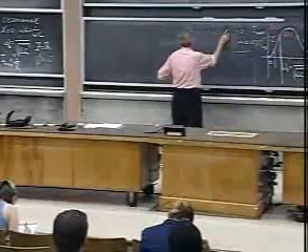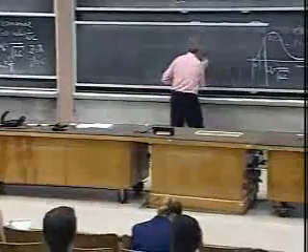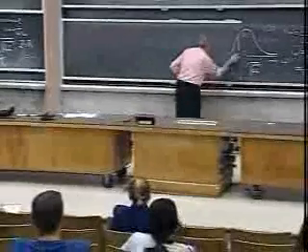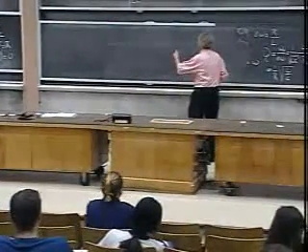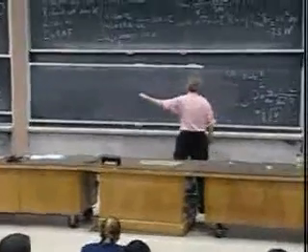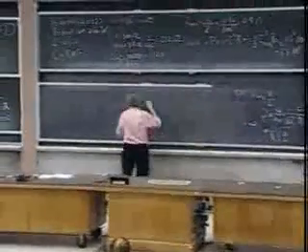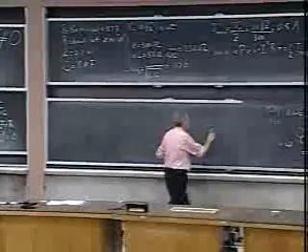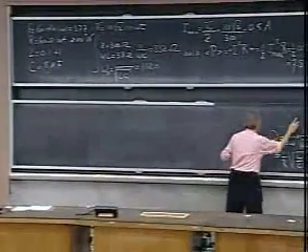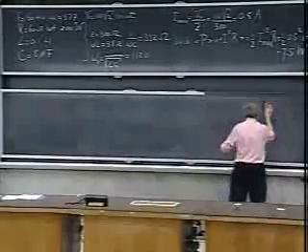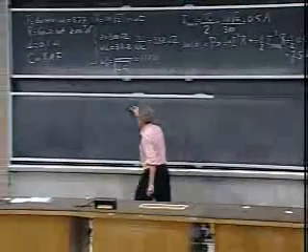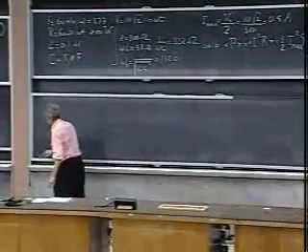If we make L larger or make C larger, then obviously you shift your resonance frequency down from 1120. And my goal is to shift it down to 377 radians per second.